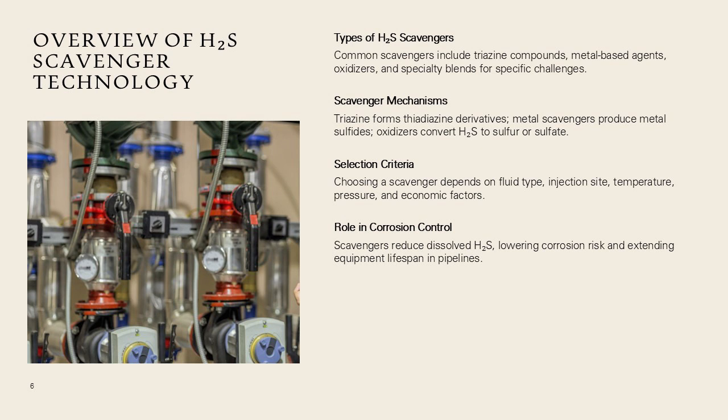The most widely used scavengers include triazine-based compounds, metal-based formulations, oxidizing agents, and specialty blends engineered for specific operational challenges. Triazine scavengers operate by forming thiodiazine derivatives through reaction with H₂S and are highly effective in treating gas and liquid streams with moderate H₂S concentrations.